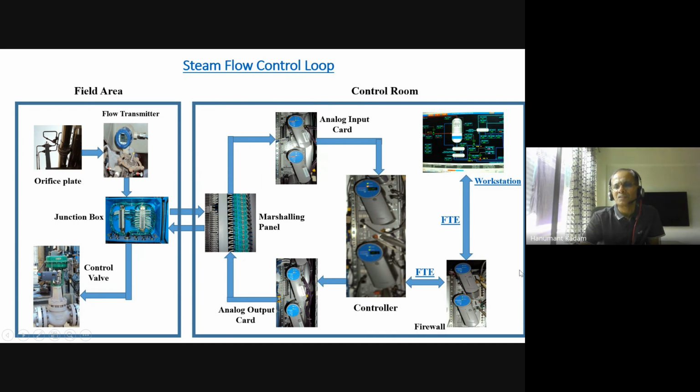So this is the control room part, where you can see the marshalling cabinet, and from the marshalling cabinet, this being an ammonia plant with a hazardous area, you can see intrinsic safety barriers, IS barriers, this side. This is a terminal strip with a fuse link, IS barriers, and from there the signal goes to the analog input card here, which is dual redundant. This is the AI card, Series C cards in the Honeywell system.